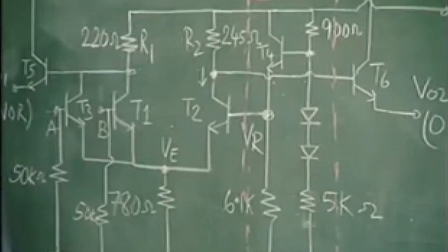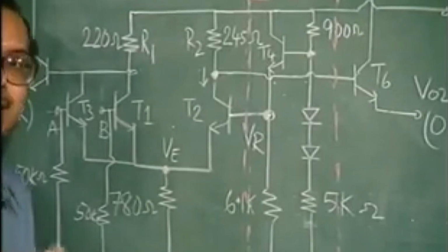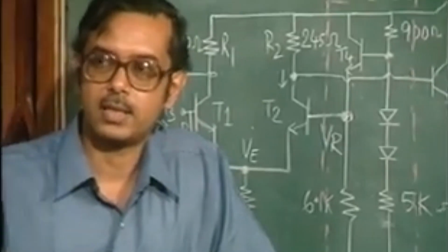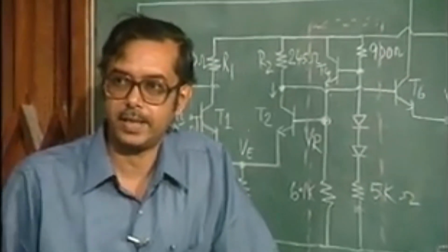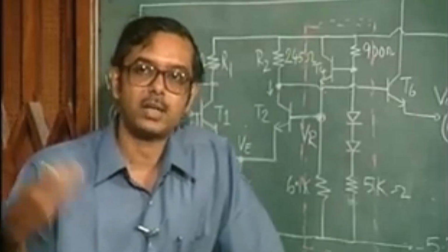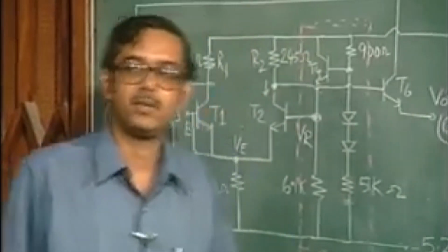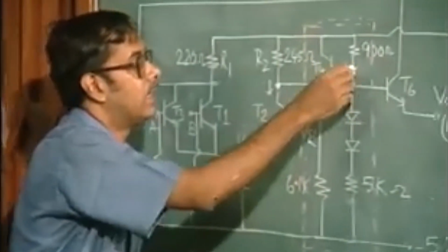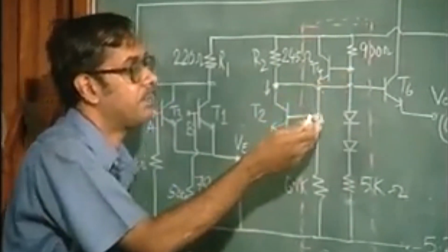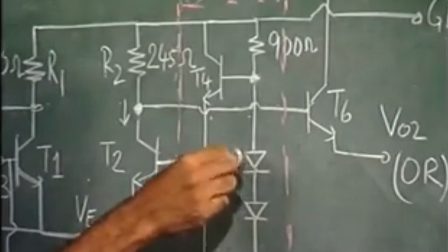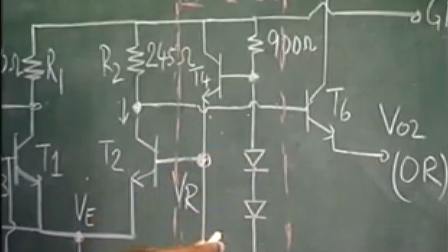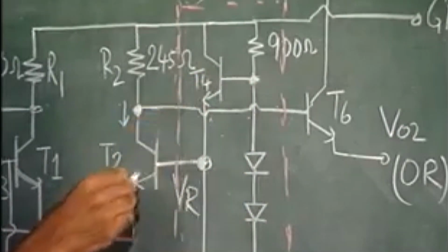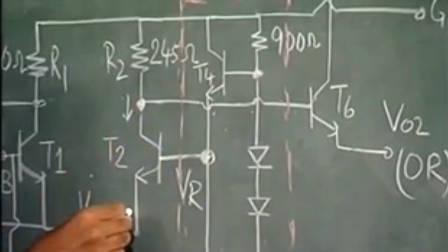You know that the base emitter voltage of a transistor changes at around 2 millivolts per degree centigrade. And when you convert that to current, because of the exponential nature, you have a lot of difference. So, when the temperature goes up, the voltage across these diodes also changes. From this point, you have 2 diodes here, and these are the 2 base emitter voltages here.